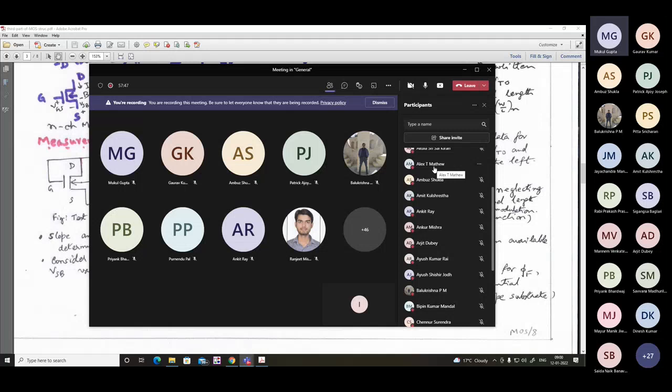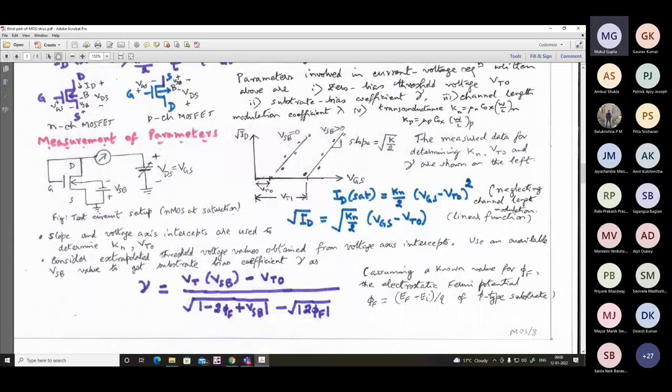Good morning, sir. Sorry, Ankit. Can you repeat the question? Yes, sir. The biasing voltages of the gate, source, drain, and body in the diagram you have shown. What is the problem in the biasing in that circuit? Once again, gate and drain are shorted. That means you will force the transistor to be always in saturation. That is for one thing. And next, what is your question? Like you told that in this circuit the source is grounded and the body is connected to a negative potential. Yes. So actually, what is the problem?